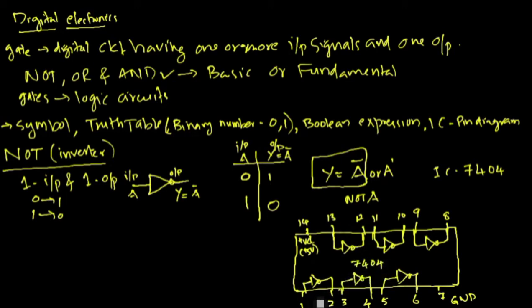To identify the pins 1, 2, etc. of the IC, if you take an IC, you can see that there is a dip or a cutting at one end of that IC. Hold the IC in your hand in such a way that this dip is towards your left.